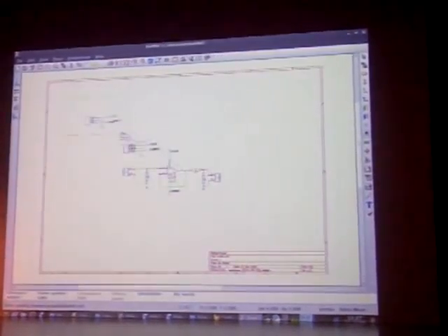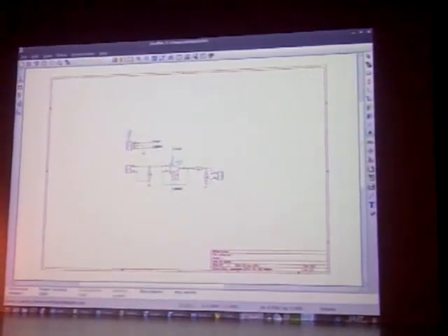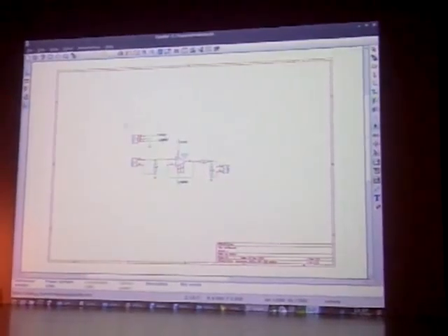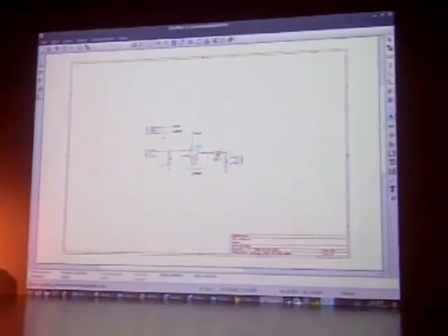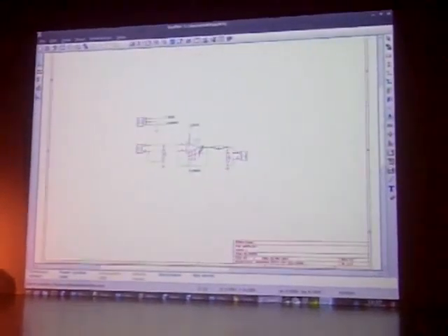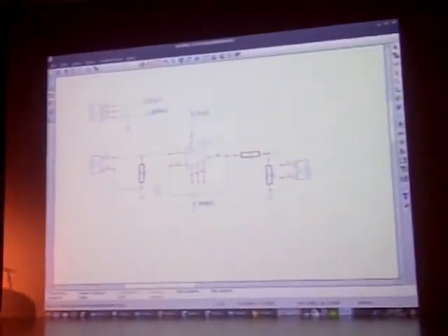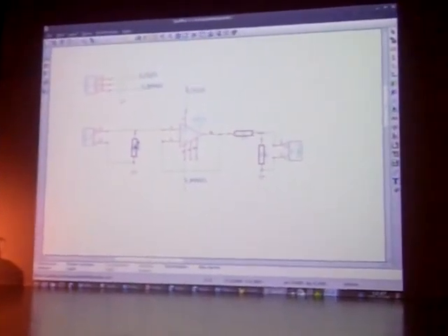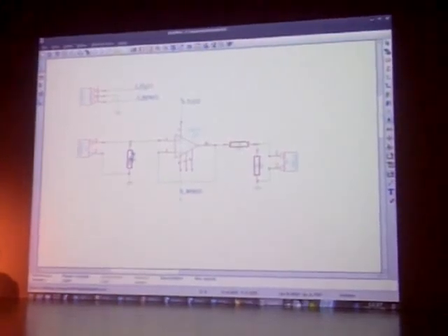Once I've done that, I can actually grab a block. If I wanted to spend the time, I could just get this power stuff and put it up in the corner to get it out of the way, so we really just concentrate on the circuit itself. A couple more things left to do. You'll notice our parts don't have values. This is just R. A couple ways to assign values to parts in your schematic if you want to.